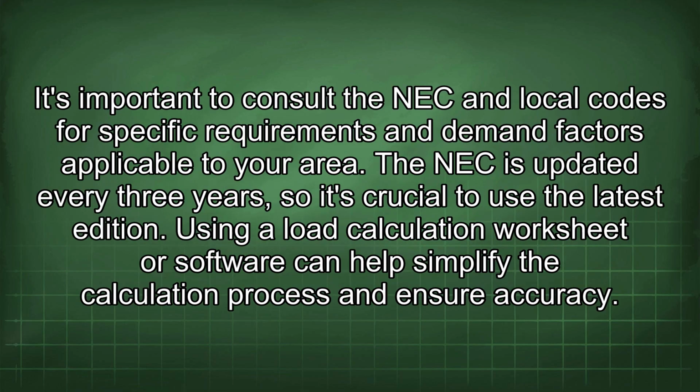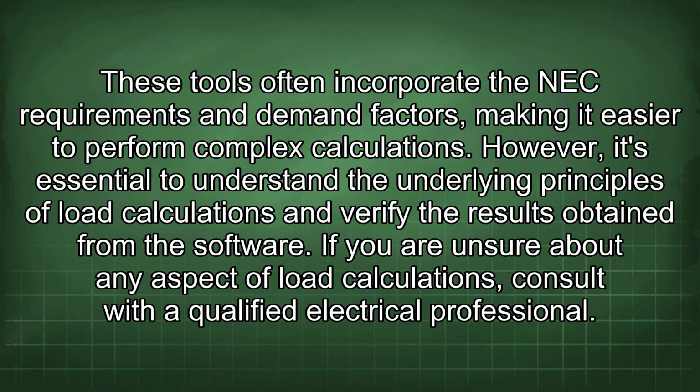It's important to consult the NEC and local codes for specific requirements and demand factors applicable to your area. The NEC is updated every 3 years, so it's crucial to use the latest edition. Using a load calculation worksheet or software can help simplify the calculation process and ensure accuracy. These tools often incorporate the NEC requirements and demand factors, making it easier to perform complex calculations. However, it's essential to understand the underlying principles of load calculations and verify the results obtained from the software.